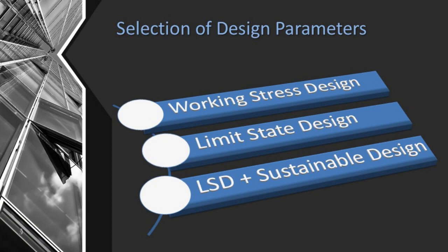So now I think we should discuss something about the designer aspects. We started doing drawings, and our senior engineers started working on the working stress method of design. So stability is the thing that had more concern. After optimizing this technique, working stress design, we came up with limit state, because in the working stress method you are basically putting a huge amount of reinforcement in it. So basically you are designing some sort of over reinforced structure.